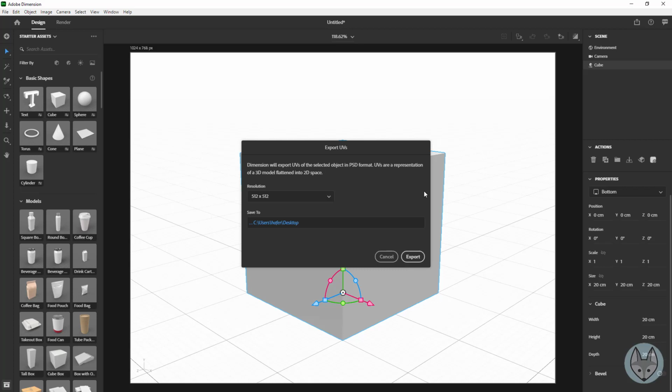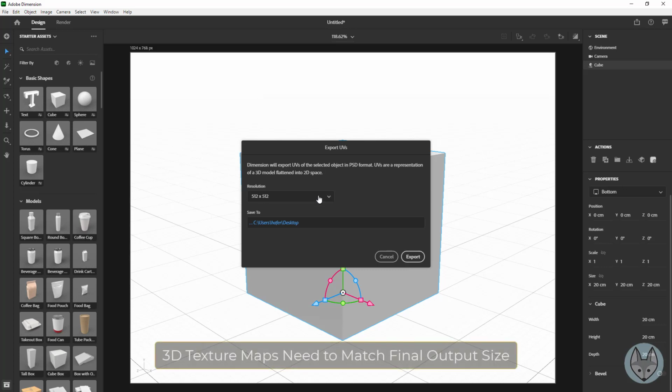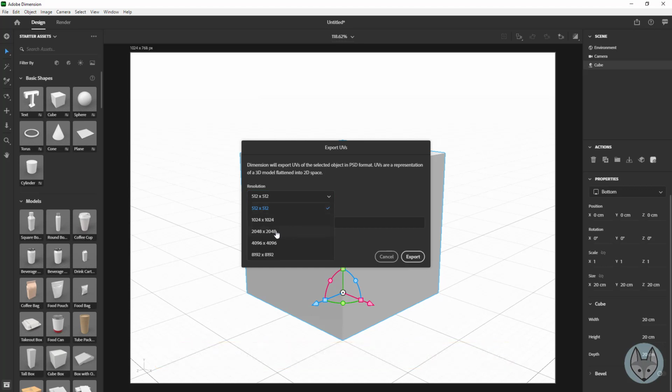That then calculates all of that and renders out to the size you want it to be. So you might need it for a small 200 by 200 for an icon at 72 dpi on a website, or you might need something that's 24 by 36 inches at 300 dpi to print a poster. And so that output resolution is where you want to make sure that your texture maps are big enough for that resolution. And that's all I'll say about it here. But for our case here, we'll be definitely safe with a 2048 by 2048.